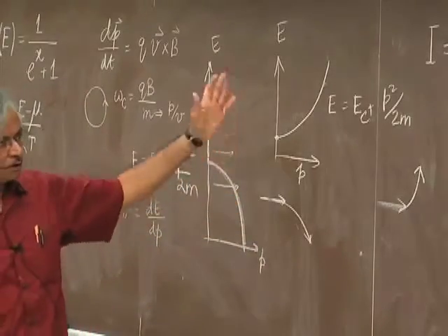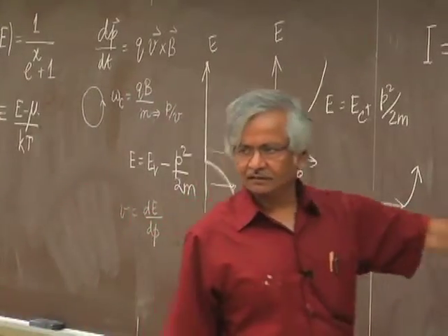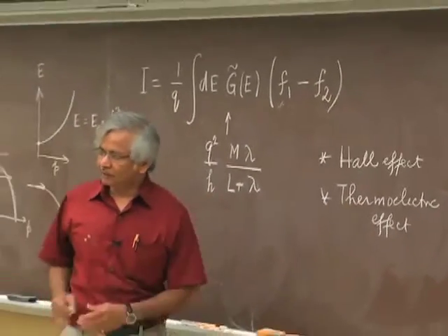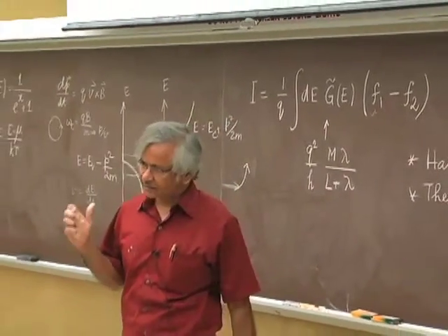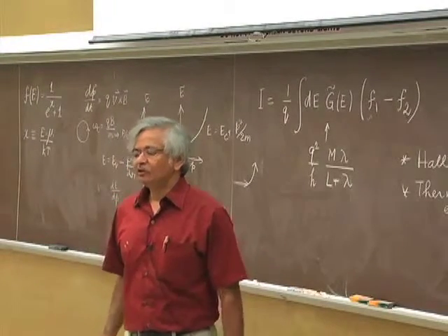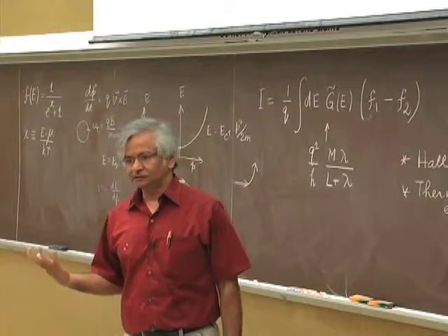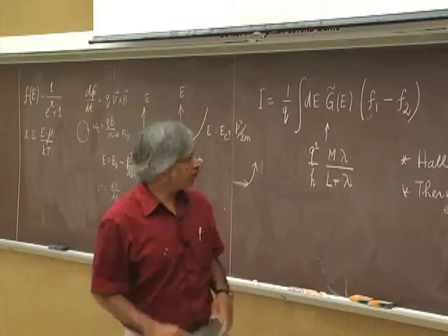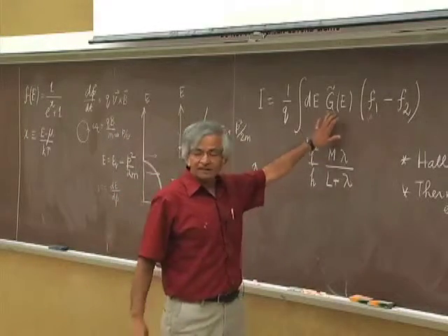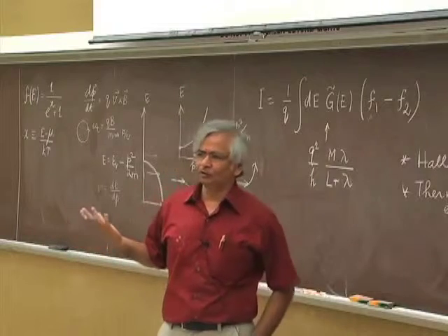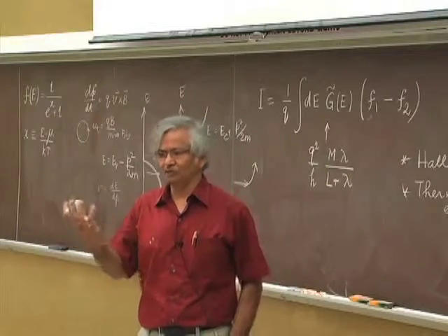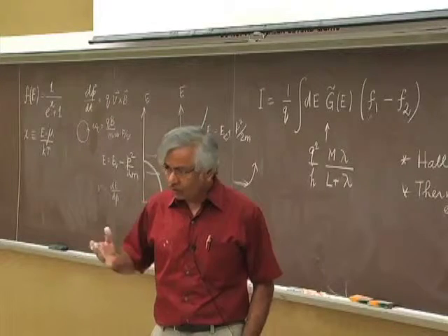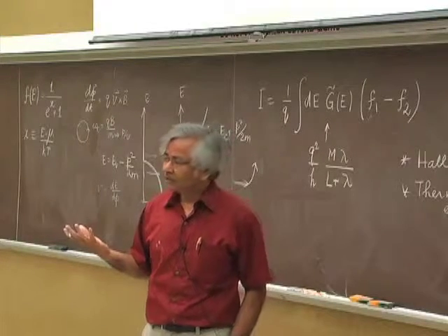But when you talk about the thermoelectric effect, which is what we are discussing, there is no real difference between the two bands anyway. One interesting related point: when you look at amorphous semiconductors, I made the point that a lot of what we are saying about density of states is applicable even if you don't have an E-K relation, for anything small or for an amorphous material.